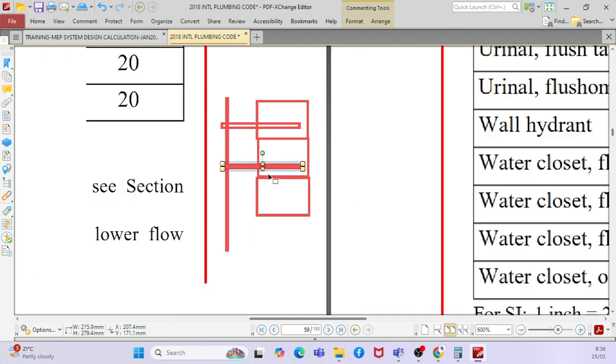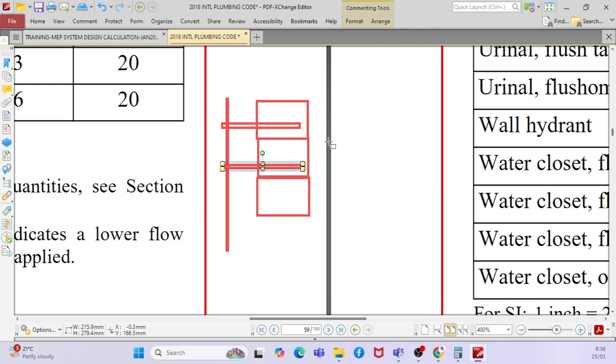In some projects, if you have a long water supply, you have a 100 mm, a 150 mm, sometimes 200 mm. For 100 mm means 4 inch, right? Yes, 4 inch pipe. That PPR is available. PPR pipe is available. Yes, PPR, HDPE.